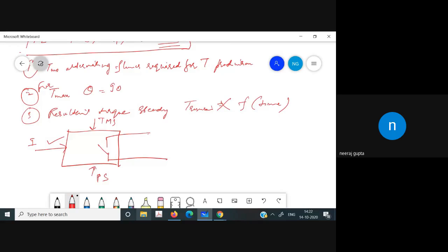So as per this conclusion, whatever we have drawn from this discussion, two fluxes are required, which are not in phase, to produce the torque. And since the input of that is only the current, how can we do that? So we are using the shading ring for that very purpose. What the shading ring will do, it will lag the flux by some angle.